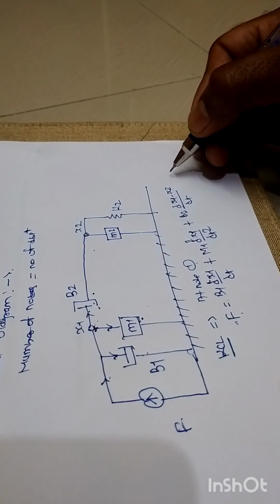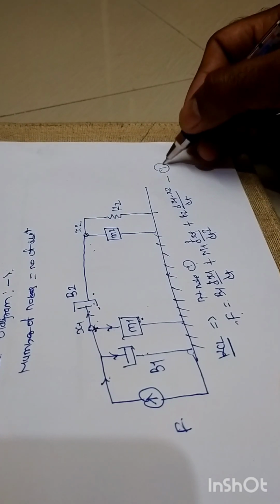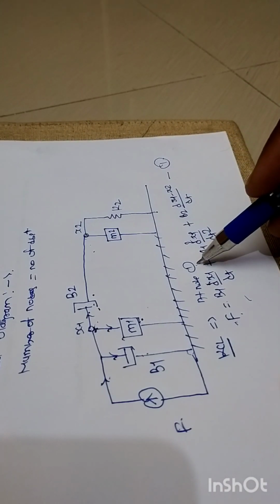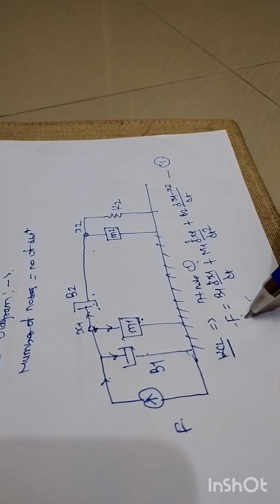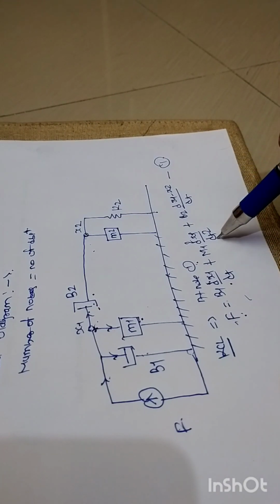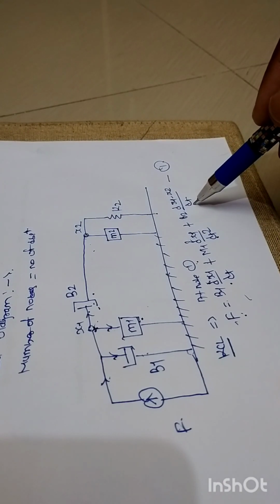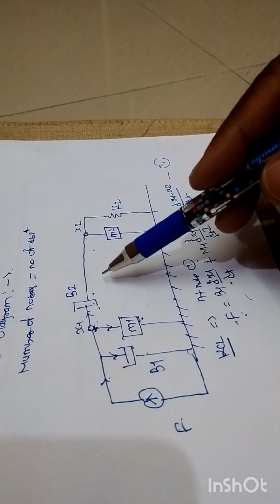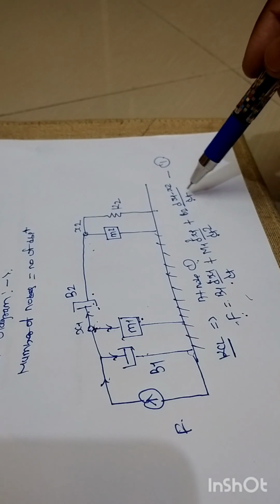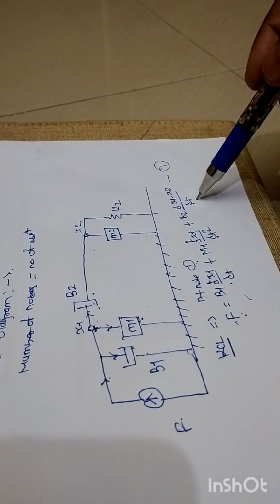So this whole equation can be treated as equation number 1, which is nothing but the system equation at node number 1. This is the incoming force. This is the system equation belonging to the damper, first order differentiation, velocity. This is the system equation belonging to the mass, second order differentiation, and this is the system equation belonging to damper number 2, that is B2, as it is connected in between x1 and x2. So the overall displacement will become d x1 minus x2 by dt, right?